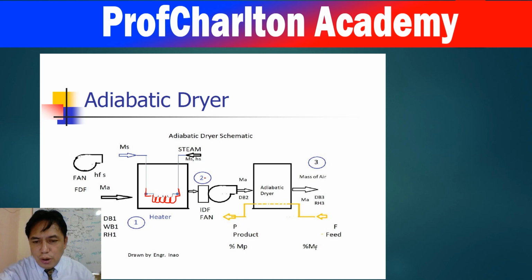Then here at point 2 is the location of the fan, and it will fan out air into this dryer. So this is the dryer, adiabatic dryer. If this is dry bulb 1, then this is dry bulb 2. This mass sub A, because mass is just constant, enters here, so there is this mass flow of air coming into the adiabatic dryer.